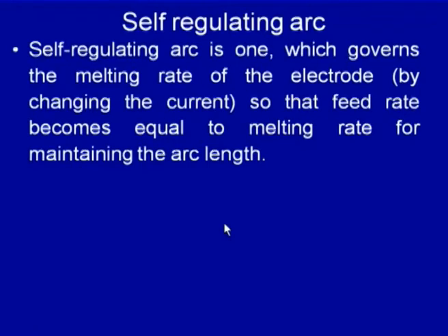Further, we will also be looking into the need of having a particular kind of insulation, and how does insulation class affect the duty cycle and the temperature conditions under which it can work successfully during the welding. We will also be seeing the different feed drives which are used for maintaining the arc length and the high frequency unit. So, going with the self regulating arc, which is established when the constant voltage type of the power source is used in association with the constant feed drive system.